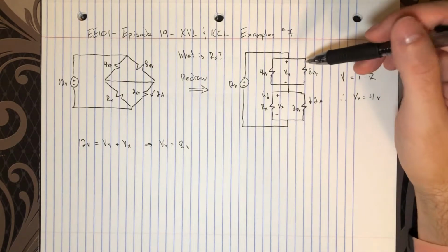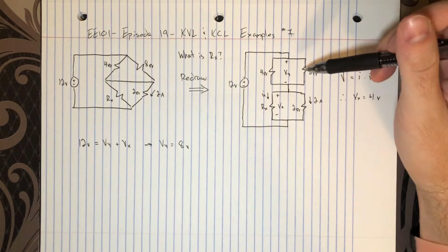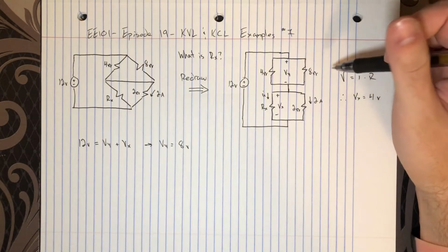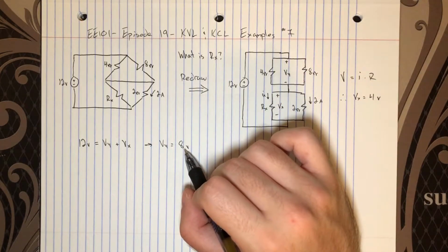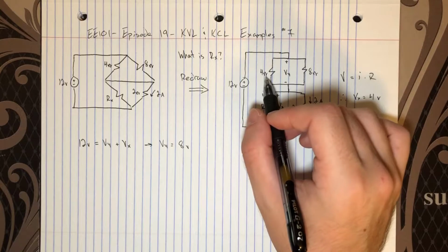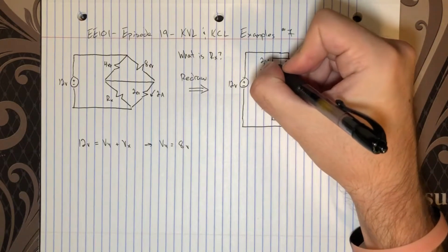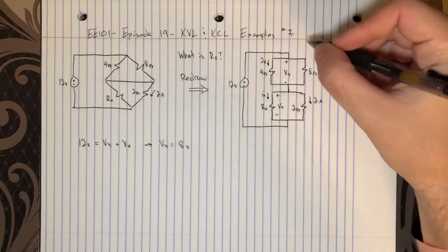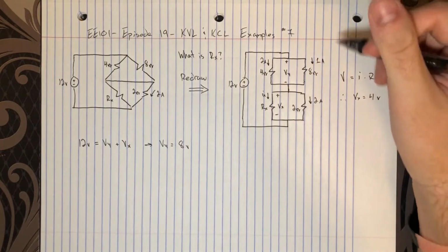And that's fantastic because now we have a voltage across 2 resistances, which means we actually have 2 currents as well. So just doing this math quickly, V over R will give us the current. So 8 divided by 4 is going to give us 2 amps in this element, and 8 divided by 8 is going to give us 1 amp in this element.